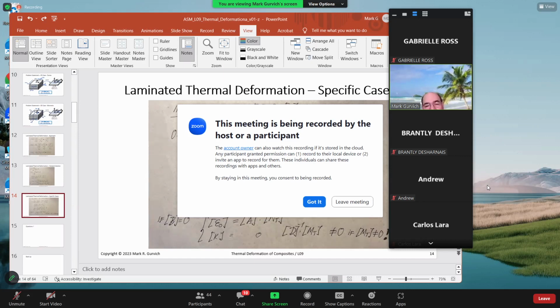So what will be our next step? We will separate them. We will put this term to the left and this one to the right. So now we have the stiffness matrix ABD multiplied by epsilon sub k equal to the matrices NT and MT. And because delta T is non-zero, the matrices NT and MT in general are also non-zero. And we know how to calculate these.